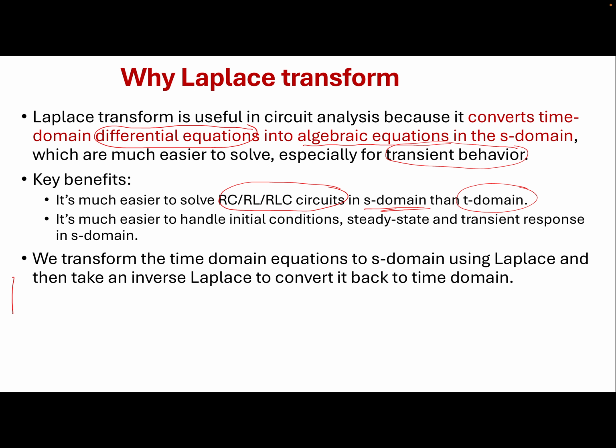So the point is, we get a time domain circuit, we convert it into an S domain circuit, which practically means I am transforming my time domain equation into an S domain equation. Once I convert that into a Laplace transformed equation, I can reconvert it back into the time domain as well. So essentially, this is what we are going to do in circuit analysis: start with the time domain, move into the frequency domain or Laplace transform, S domain, and then move back to the time domain.